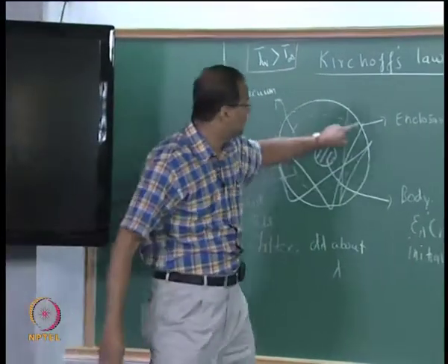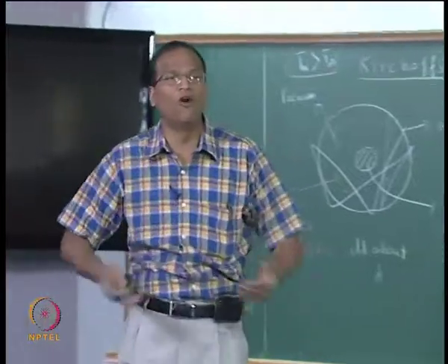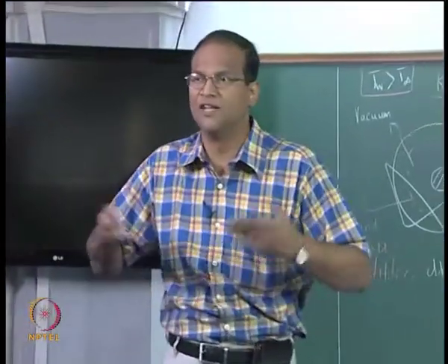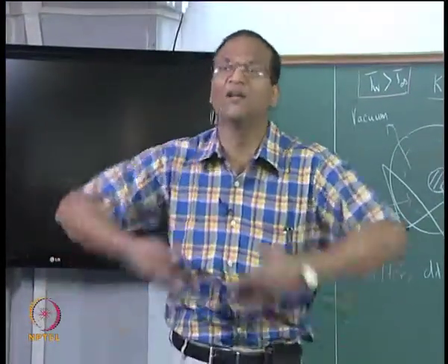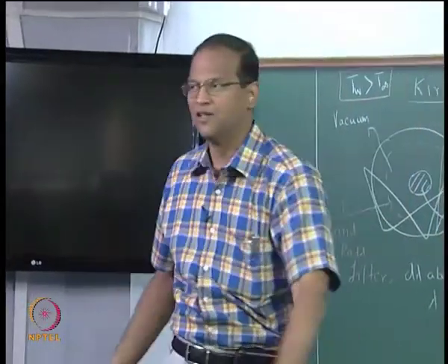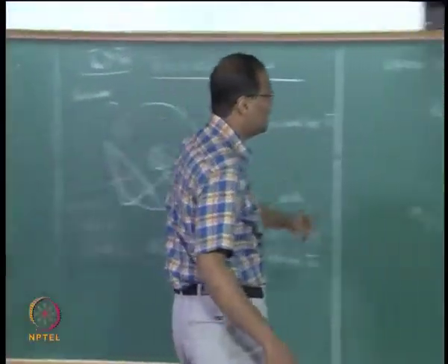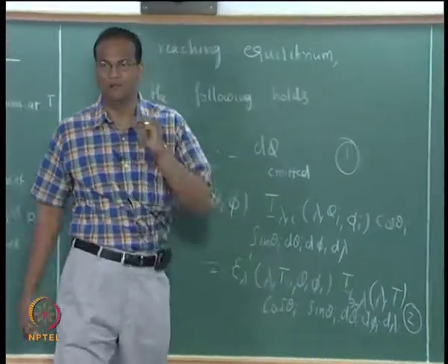and since this is also at the same temperature as this, I lambda I corresponds to uniform and isotropic radiation from the walls of the enclosure, which can be deemed to be radiation from a black body at a temperature T, which is the same as the temperature of the small body within the enclosure. Therefore, I am allowed to change I lambda I to IB lambda.